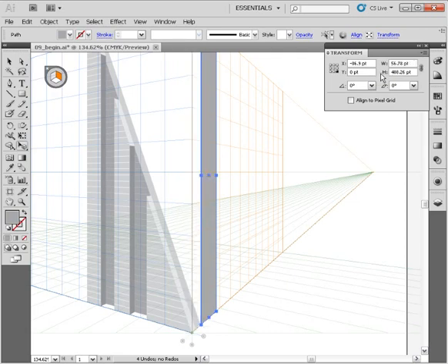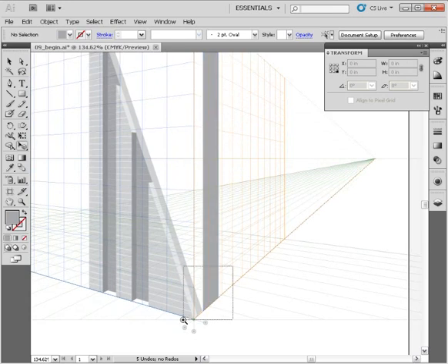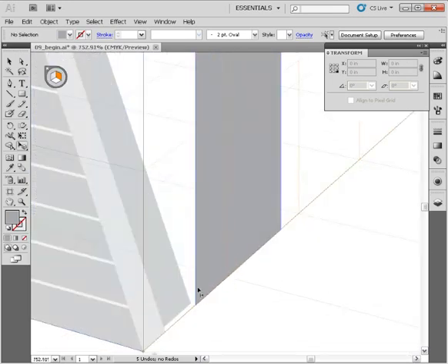I'll hit enter, and you can see that Illustrator has subtracted that from this left side because we had one of our right side reference points set. So we've input that mathematical calculation, we have subtracted those 2 sides, and essentially figured out exactly where this should go. Now all that's left to do is inset this some. It looks like we're inset 1.71 points here on our y-axis. So let's subtract minus 1.71.